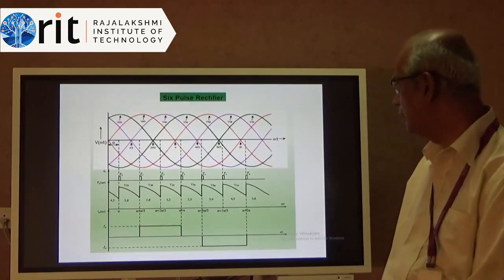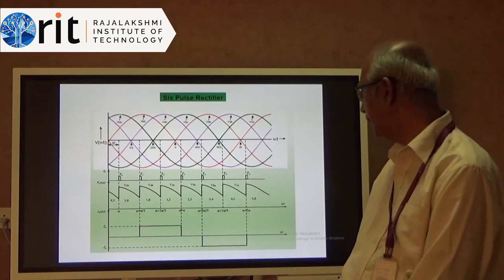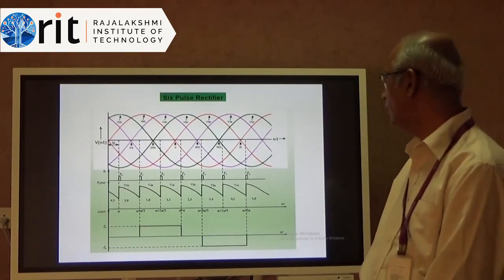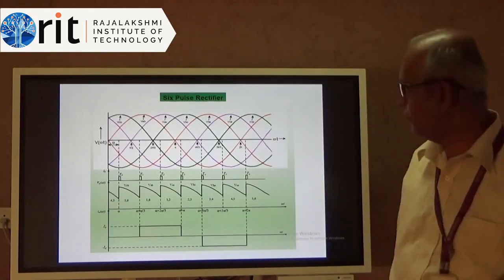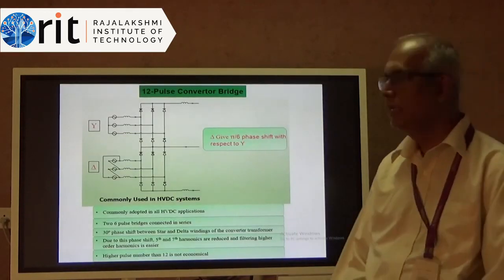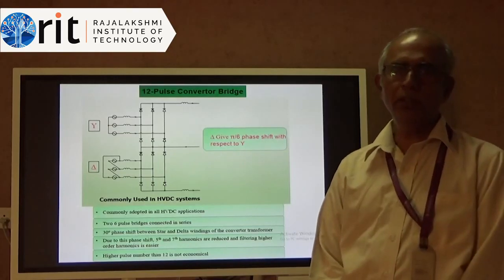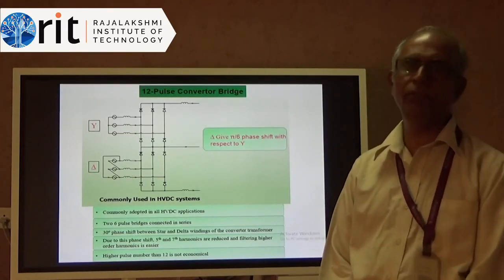We have either a rectangular DC for 120 degrees or a rectangular negative minus ID for 120 degrees, and the voltage waveform is as we have just now seen, that is a waveform with a DC component but an additional AC ripple over the DC component, right? For this, now let us say we want to control a normal DC motor, a 6 pulse rectifier is more than adequate for the purpose.